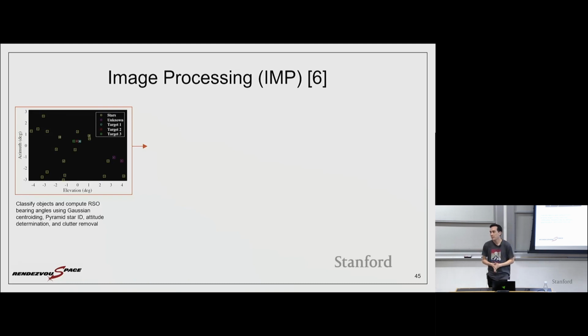Oh, go ahead. I was just wondering, would it be possible to get that coarse estimate outside of GPS? Like, could you do vision based on looking at the Earth or something? Yeah, you totally can. If you have a model for the Earth, you could look at land masses and say, okay, this is what it appears like in my camera frame. I have a bunch of unit vectors to features on the Earth instead of spacecraft, and I can back out my own position.